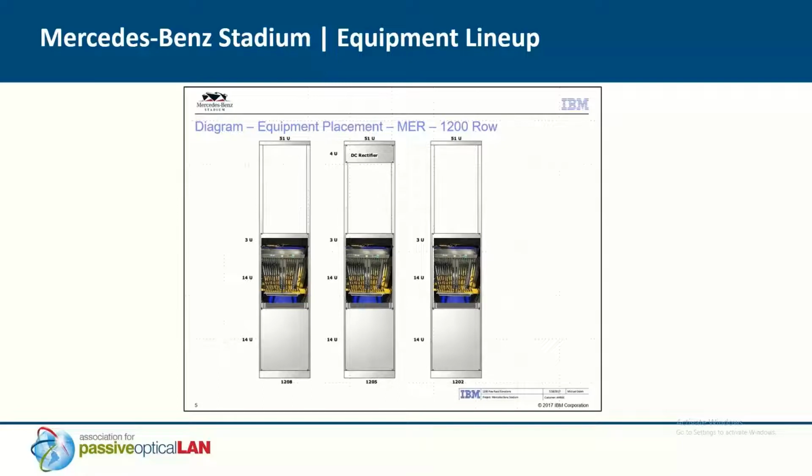They've got 3 different chassis, several different core providers, and each of those chassis is only using up 14U. We're not talking dozens and dozens of racks. Now they do have many other racks out there for other equipment, but the PON itself requires very little footprint. And again, a very small amount of single mode fiber as compared to what the copper requirement would be.